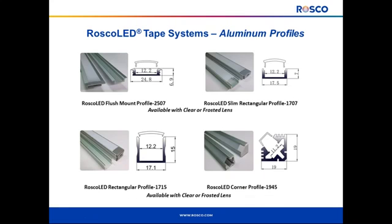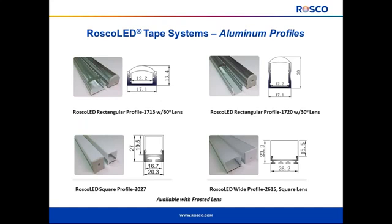I mentioned earlier in the presentation, we offer a range of aluminum profiles. We've got flush mount profiles and surface mount profiles, both of which are available with a clear or a frosted lens. And then we've also got some somewhat unique profiles in the case on the top 2 on this slide. These have beam shaping lenses. The one on the left is actually able to achieve a 60-degree beam angle, and the one on the right can achieve a 30-degree beam angle. And if you recall, these were used in that arched ceiling in the ballroom in one of the earlier examples that I showed. We've also got some larger profiles with frosted covers, some of which can be suspended above a work surface or an area.